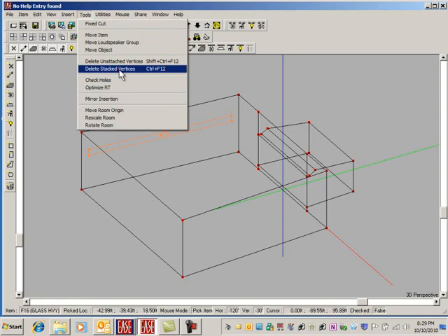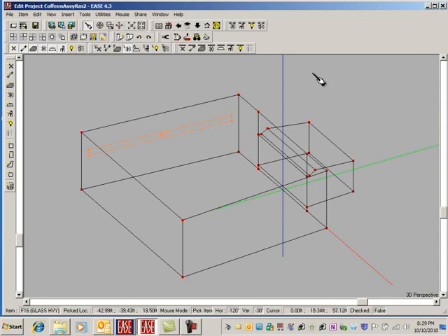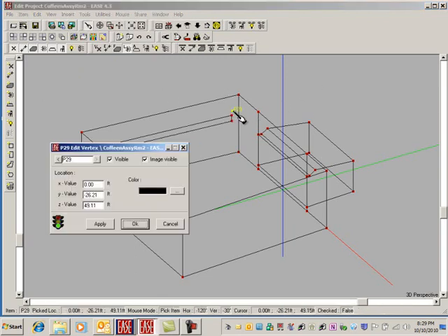And the easiest thing to do is mirror this, and it's on the other side there. We'll move this so we can see it, create an edge. This is what we did before. Over to there. Okay. We can move this a little bit so we can see it a little better, and we can extrude this edge. As I recall, we went up 12 feet.